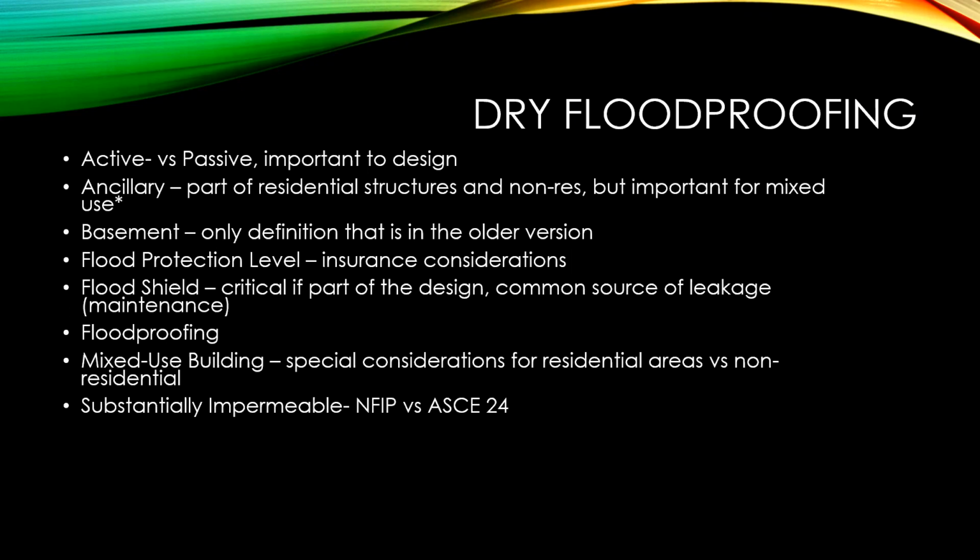Basement was the only definition that was in the older version of Technical Bulletin 3, and now Technical Bulletin 3 has a lot more definitions. So I'll be showing you an overview of this update, and it really expanded on how dry floodproofing is done, how these designs are made, and they've broken it down into a process. Flood shields are a critical part of the design. They're often also a source of leakage.